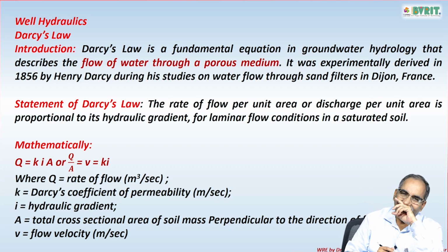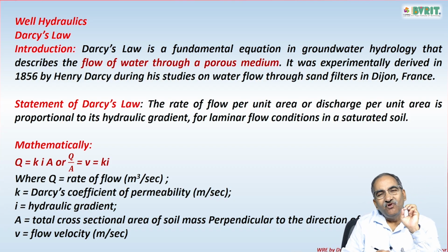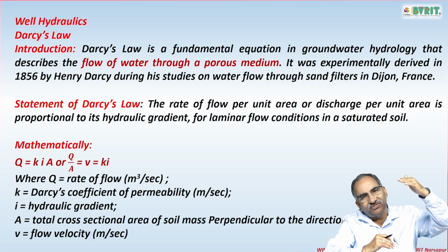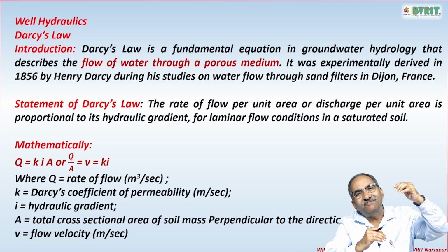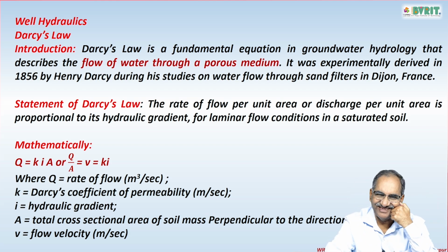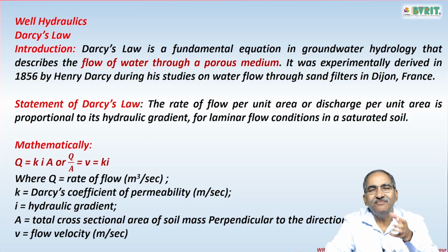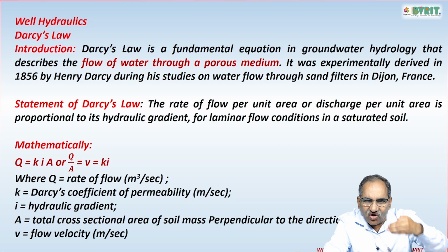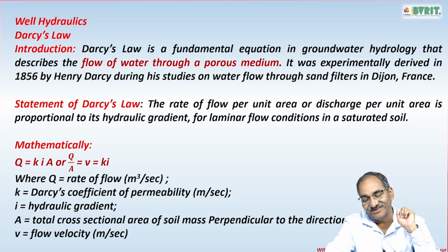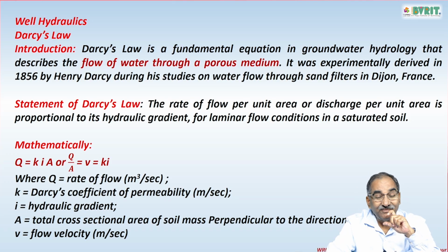So what is that? It describes the flow of water through porous media, mainly through the soil pores, how this water travels. That is being given by Darcy's law. Porous media is nothing but the soil structure. So through soil, how the water flows, that is given by Darcy's law. It was derived experimentally by Darcy.